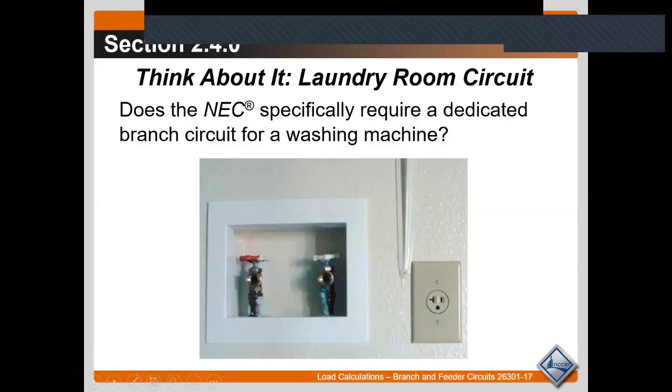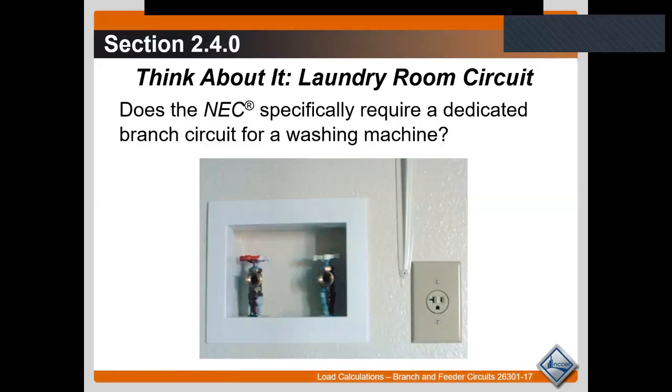Now, I thought in my mind when I saw that single outlet, does it require a single outlet? And the reason we use a single outlet as shown in here, I'm going to increase this real quick. Let's see, share again, there we go. All right, why do you think we would use a single outlet versus a duplex outlet in the laundry for that one?